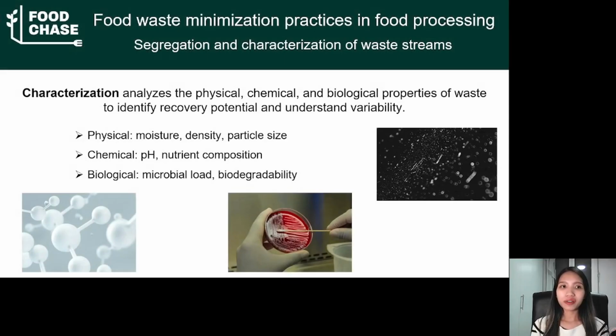After the segregation, the characterization is carried out to analyze the physical, chemical, and biological properties of waste to identify recovery potential and understand variability. Physical factors include moisture, density, and particle size. Chemical factors include pH and nutrient composition, both macro and micronutrients. Biological factors include microbiome load and biodegradability.